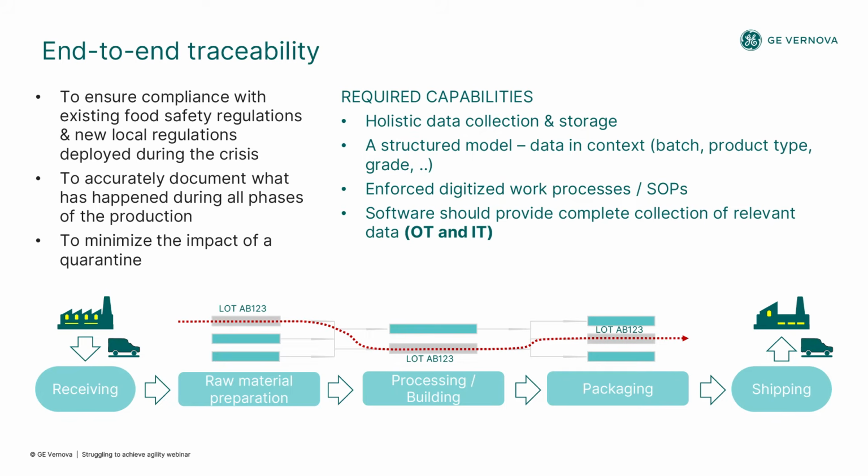And then what's the raw material that started? What process order did it start being consumed in? What process order did it end up being consumed in? And what are all the batches in between that I need to put on quarantine to check and make sure that nothing is wrong with them based on some quality information that we had? The smaller you can make that quarantine, the much better off you are, right? Because you're minimizing the potential waste. And driving the folks through proper operating procedures can impact your ability to make quality product, and that end-to-end traceability is critical in that.